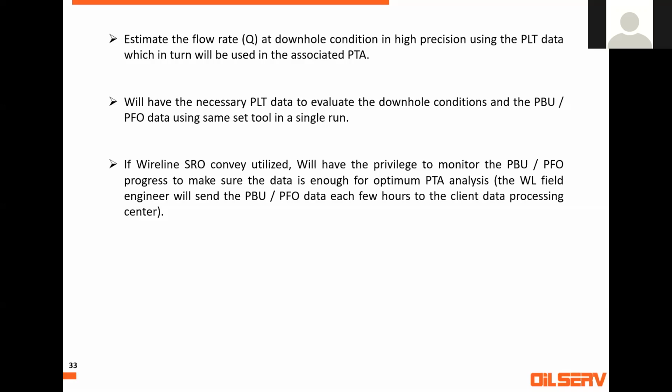I saw some major clients doing pressure buildup or pressure fall off, especially pressure buildup, in real time using wireline, even though they spend more money. They can get data every 2 hours from the wireline engineer and put it in the Saphir software to monitor the progress of the buildup and see if they have sufficient data.